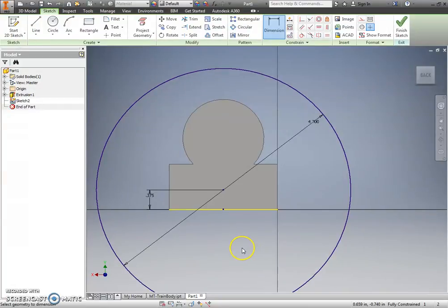And this is where it gets maybe a little tricky, but if you noticed, once I put that geometric constraint, this yellow line popped up, that is taking this geometry and bringing it onto my sketch. So the fact that these aren't all yellow means that that geometry isn't on my sketch. It's not a part of my sketch if I went in to try to extrude something or anything like that.